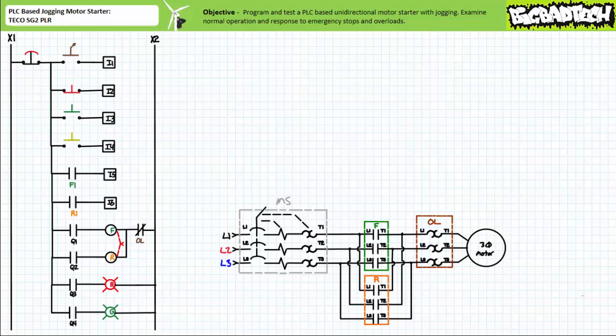This hardwired connection between the 2 contactor coils and the normally closed set of overload contacts allows the overload to have the last say as to whether the motor is energized or not, and never surrenders complete authority to the PLC. Wired in this fashion, the normally closed overload serves as a means of directly de-energizing either contactor coil in the event of an overload without the necessity of resorting to any programmed instructions to do so.